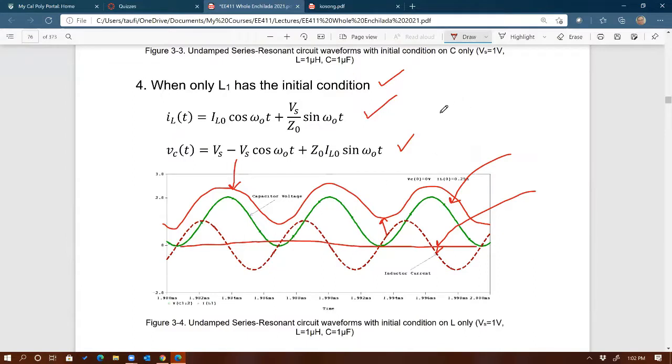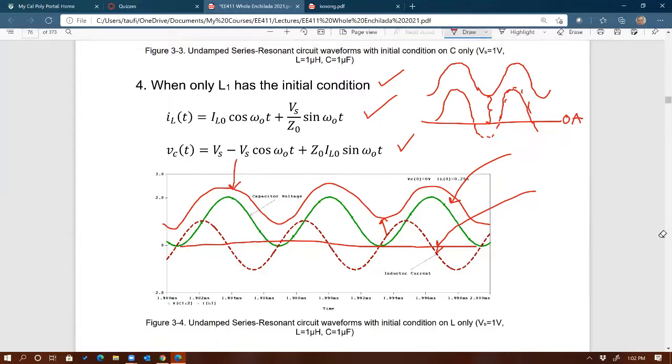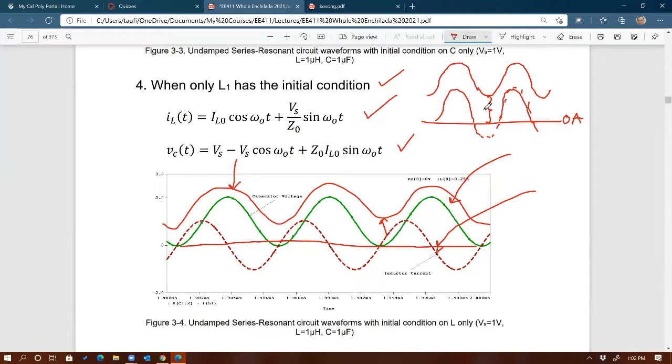So having a sine wave is very important, but you also want to make sure that the sine wave crosses zero, like that. If that sine wave is up here, then you would never get 0 amps or 0 volts. Does that make sense? Yes. So that's why paying attention to offset is important as well. Any question on that?